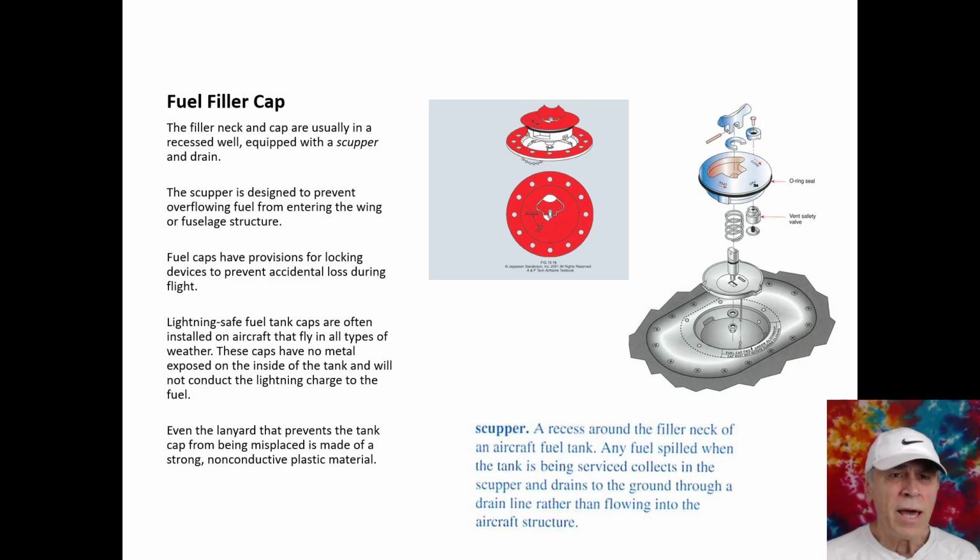Lightning safe fuel caps are often installed in aircraft that fly in all types of weather. You certainly don't want lightning to hit your fuel tank. Something could happen there. These caps have no metal exposed on the inside of the tank and will not conduct the lightning charge to the fuel. Even the lanyard that prevents the tank cap from being misplaced, you can see the chain here, that's the lanyard, even that must be made of a strong, non-conductive plastic type material.